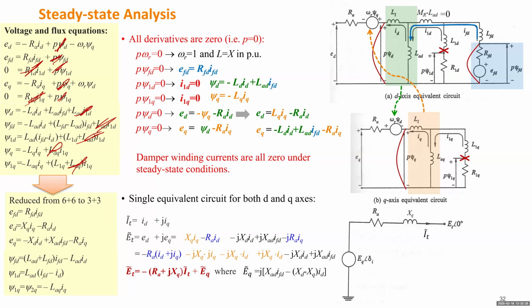So you can have a power system operating at like 55 hertz, right? If that's the case, it will be not 1, but for BPS or BES, based on NERC standards, that frequency should be very close to 60. And if you consider automatic generation control, that frequency needs to almost always go back to 60 hertz for any static condition. So it may not be an accurate model, right?